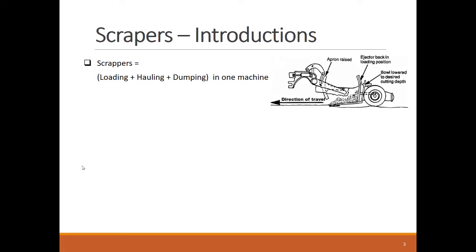Scrapers are designed, in favorable operating conditions, to perform the whole typical cut-to-fill cycle by themselves by loading the soil, hauling it, dumping it, and returning back to the cut area. Scrapers are like transformers. They have the mechanical means in their big bowl, or tummy, to load themselves without the need for the help of a loader or excavator.